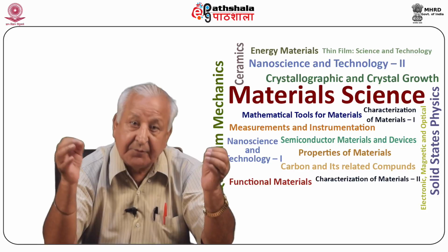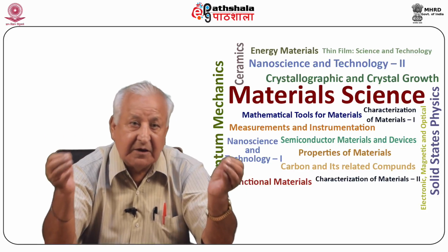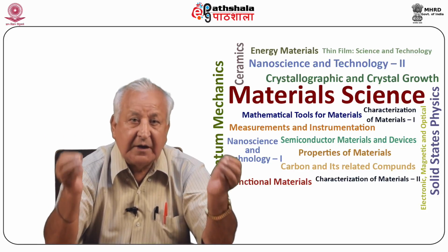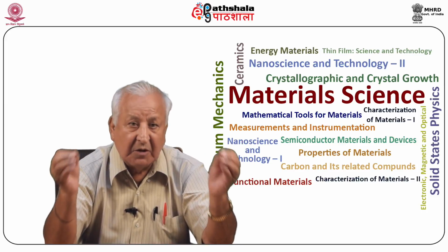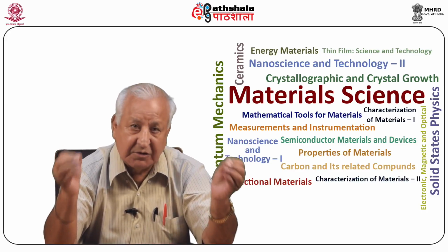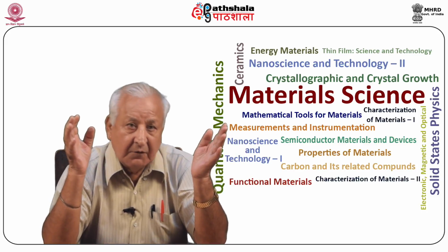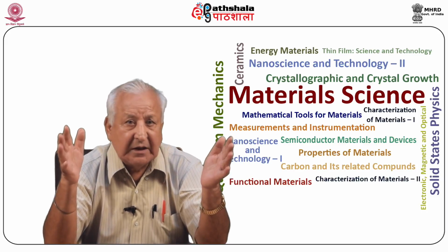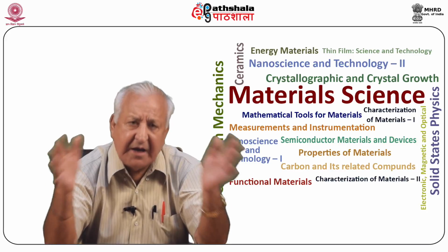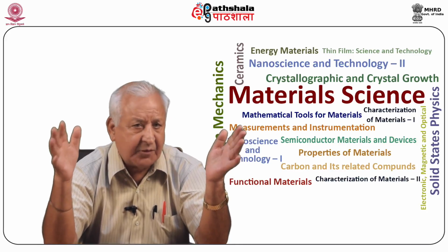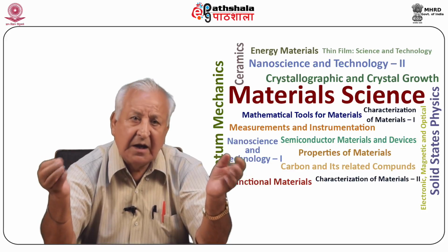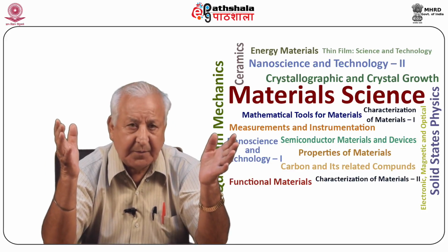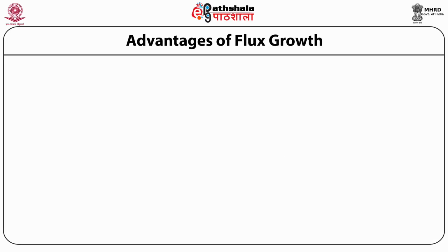Crystal growth then proceeds at relatively low temperatures, often as much as 1000 degrees centigrade below the melting point of the solute. Flux melt growth is achieved by using either of two types of processes: growth by spontaneous nucleation and seeded growth.